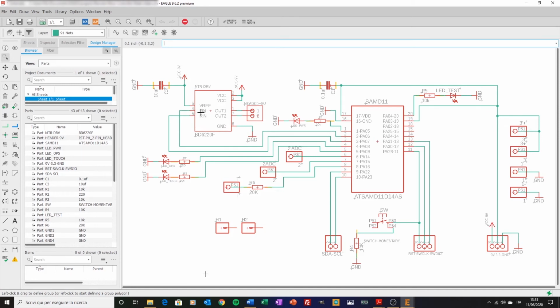Then we have pins 4 and 5, which are connected to PA6 and PA7 on the MCU. These are the forward in and reverse in, and these are controlled by the MCU via timer PWM. Then we have pins 1 and 7. These are the outputs of the motor driver, connected to the JST header, which then connects to the DC motor.